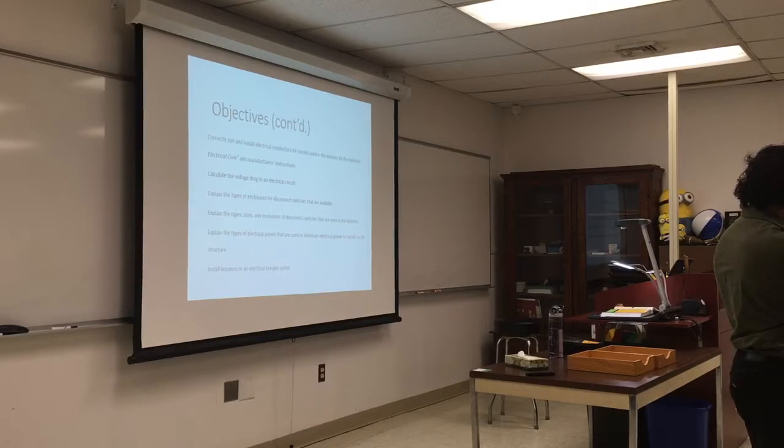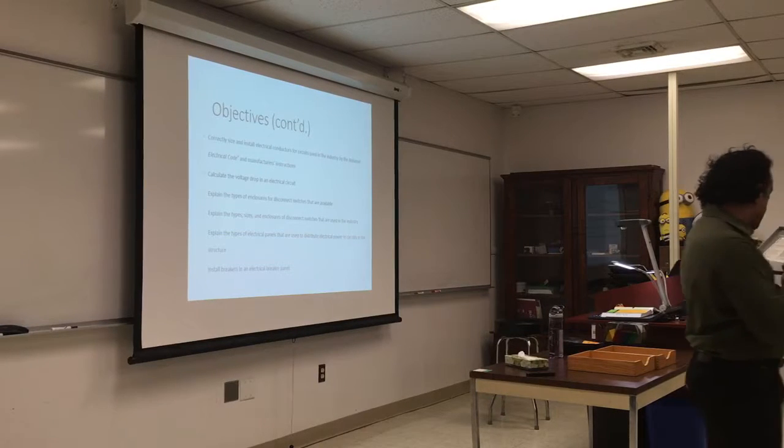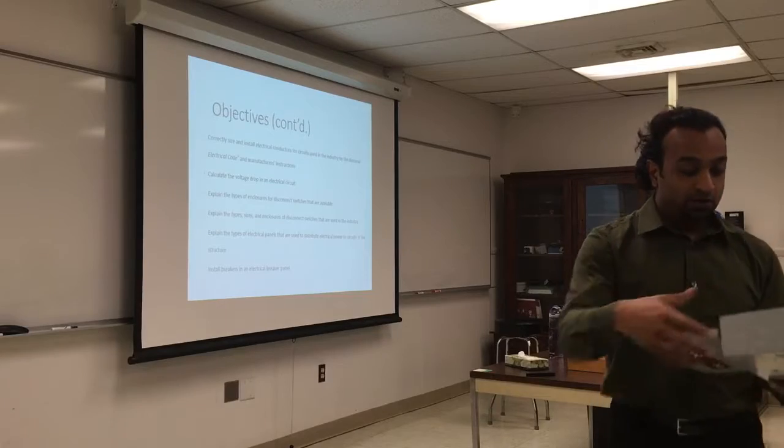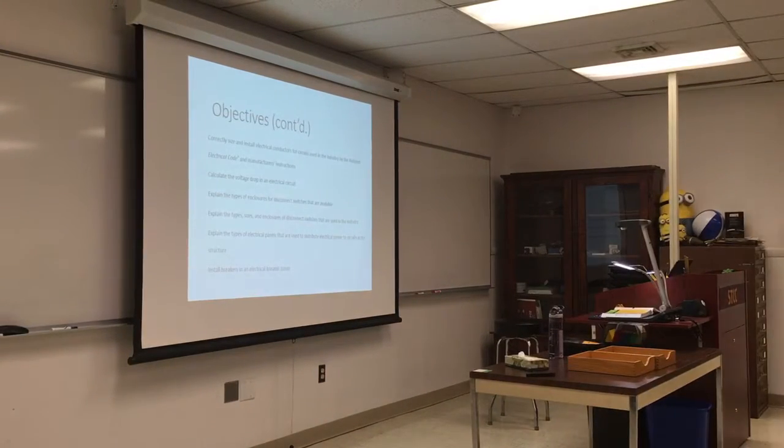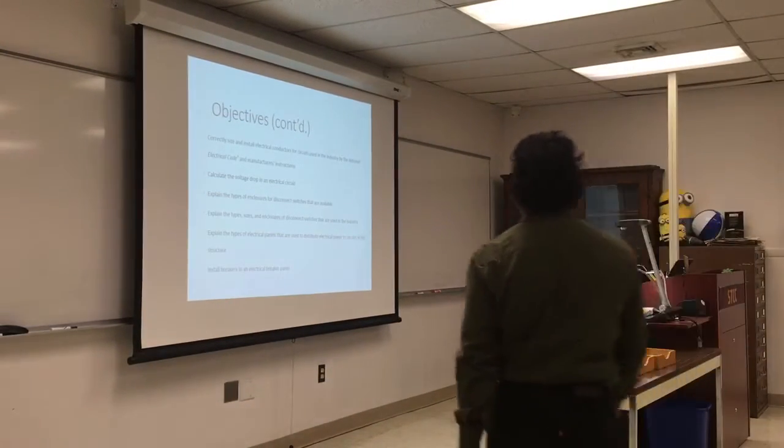You also can see the volts, the maximum. This can be used for 240 volts, 1 phase, or 240 volts, 3 phase. They give you also the horsepower rating. And this is an indoor enclosure, type 1. Fuse terminals. They also give you the limitation of temperature, 60 or 75 degrees Celsius. So I'll pass it along so you can look at it and see what it looks like. Make sure you skim over the label to see what information is there.